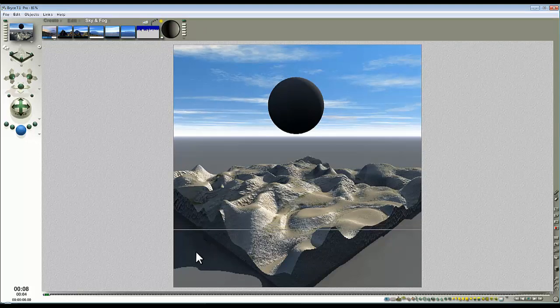This banding effect is because we've only chosen a quality of 16, which means we've only got 16 simulated light sources generated in the dome of the sky. If you want to get rid of the bands, you can increase the quality. It will slow your render time down.